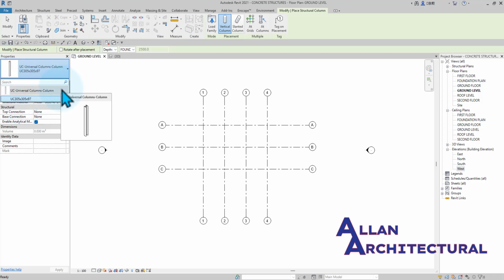So that brings us to being able to select the right template. If you had selected a structural template in there, you're going to notice you would have some types of columns in there, unlike this default template I selected at the beginning. So that's just one thing you need to know. So what we need to do now is load in some concrete columns.